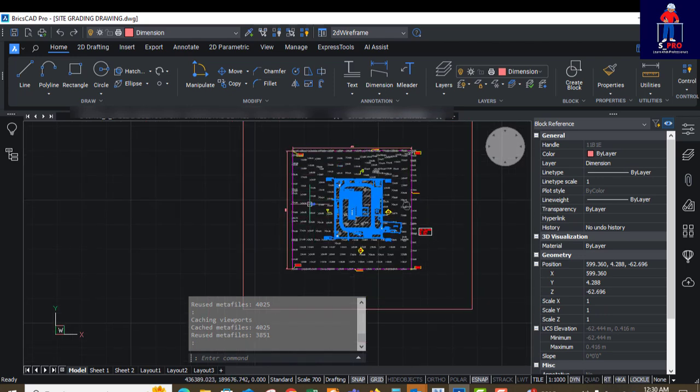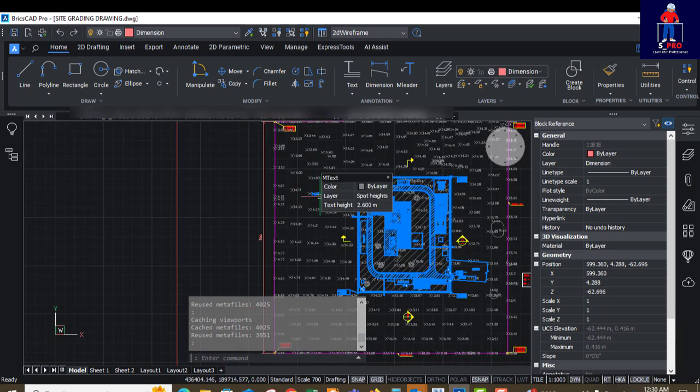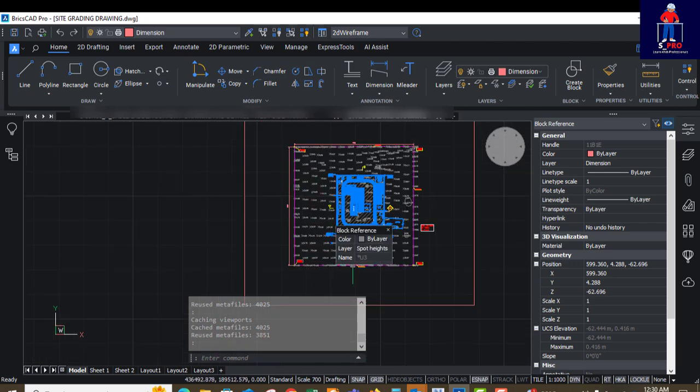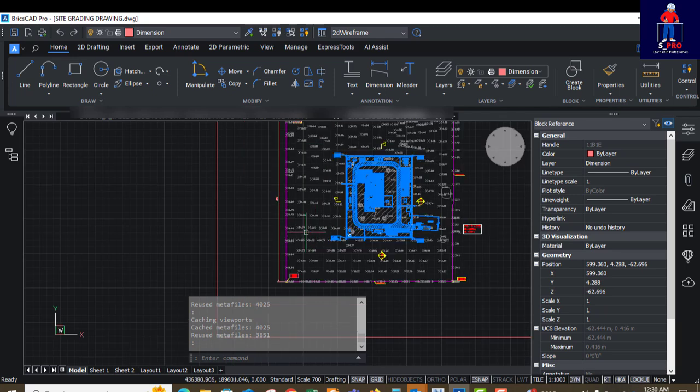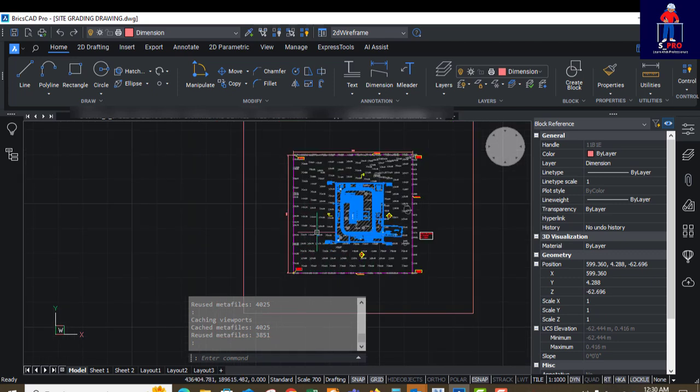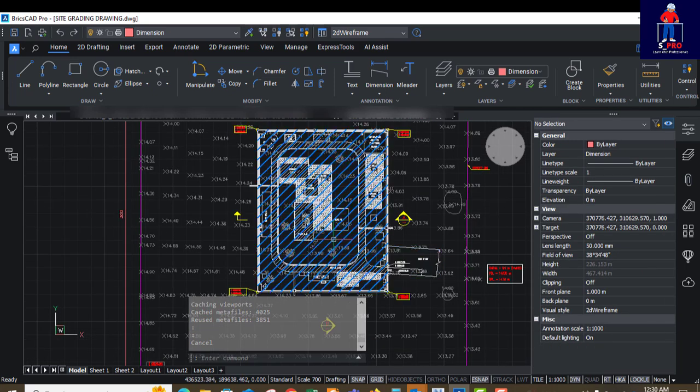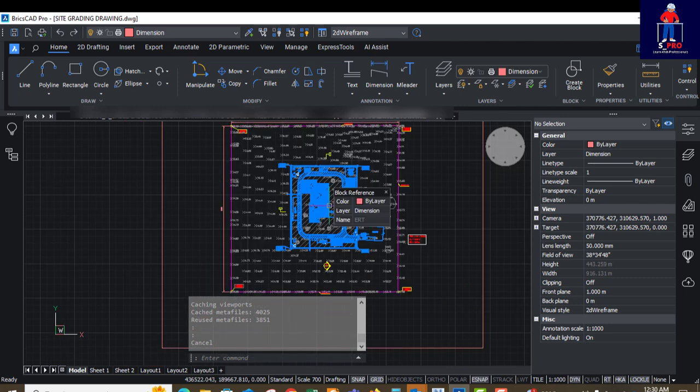From this drawing, one could tell whether the place is flat land, or it has some hilly portion or so. But you cannot tell if the place is prone to flooding, or if there is a river somewhere where you can channel your water. So when you are preparing your checklist for your site visit, because each site visit has what we call a checklist, for you to prepare checklists are those things you need to check at site.